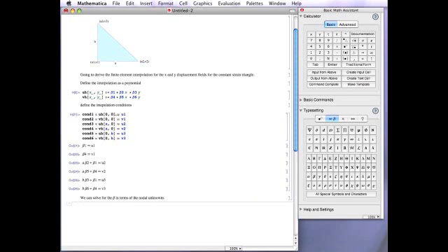So to do that, we need to solve these 6 equations for the 6 betas in terms of the u's, the other terms, the a and the b and the u's, okay? The way we do that in Mathematica is this built-in Solve function, square braces. First you put in the equations. It's actually a list of equations and then a list of unknowns we're solving for. If it's one equation, you just type in the equation and then the unknown. But here we have 6 equations. We're going to put them inside the curly braces: condition 1, condition 2, condition 3, condition 4, condition 5, and condition 6. We're going to solve for all those in terms of beta 1.